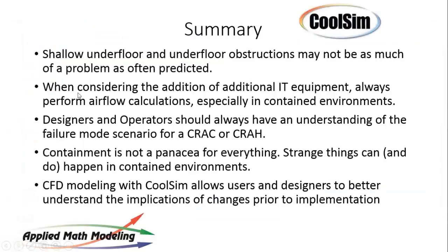So that's what we wanted to talk about today. I guess a couple of points I'd like to make. Shallow underfloor and underfloor obstructions might not be as much of a problem as often predicted. I often hear people saying, well, I don't have a 24-inch floor, therefore I can't do this or can't do that. We've just shown you a megawatt data center, 6,000 square feet, with a 15-inch floor and a lot of impediment. And one of the things we were showing is that the airflow was better with the blockage than it was through the tiles, more uniform with the blockage than without it.